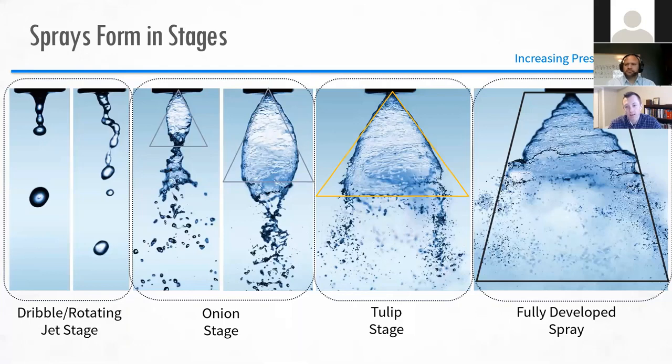And I think that goes a long way towards showing not only a liquid core or sheet leaving the nozzle, but then atomizing into first some ligaments. If you look at maybe the middle of that image, you can see some long strings or strands where the liquid is starting to break up, but it's not yet droplets, and eventually becoming droplets. So it's a nice way to visualize the spray, whereas with a flat spray, you would have a similar process, but you can't visualize the three-dimensionality of the spray as much. And with a full cone spray, there's so much happening across the spray pattern that it's harder to visualize as well.